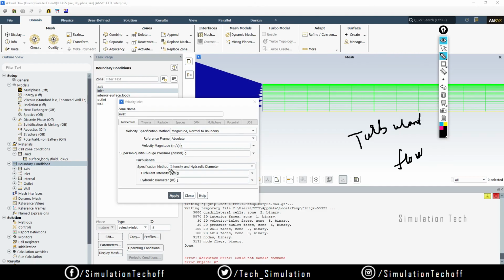So totally you have two things. If you give a factor of 5% turbulence intensity, you have a low turbulence, meaning there is not much disturbance at all. If you increase this factor to between 20 and 35%, we call it a medium turbulence.